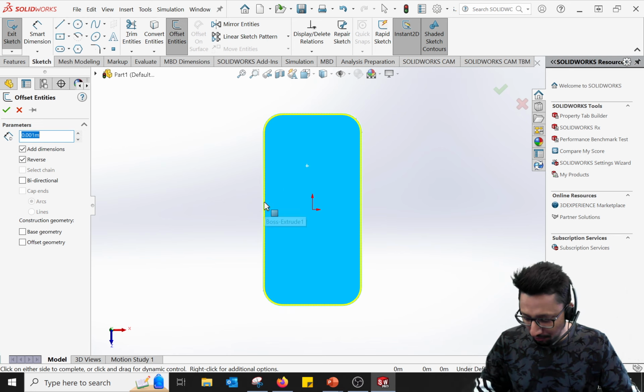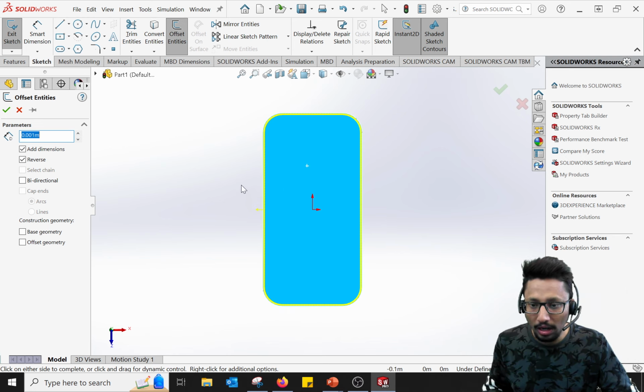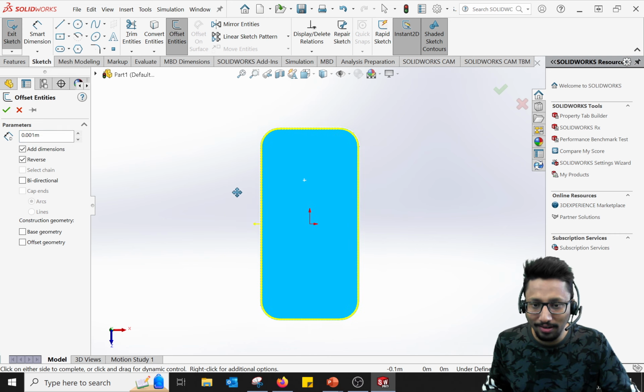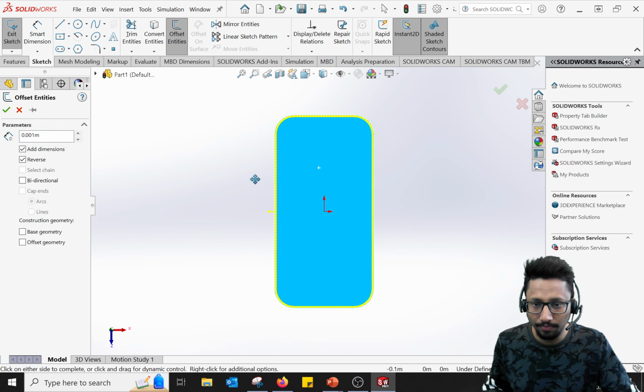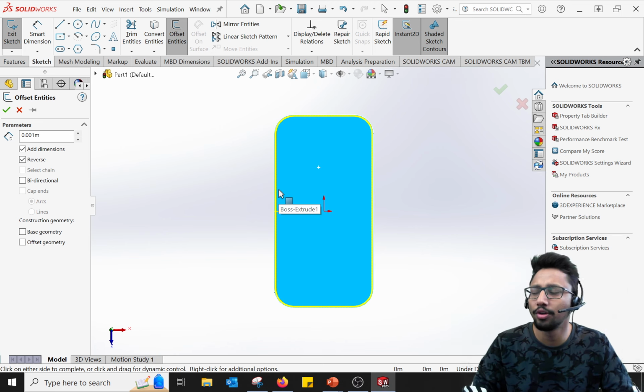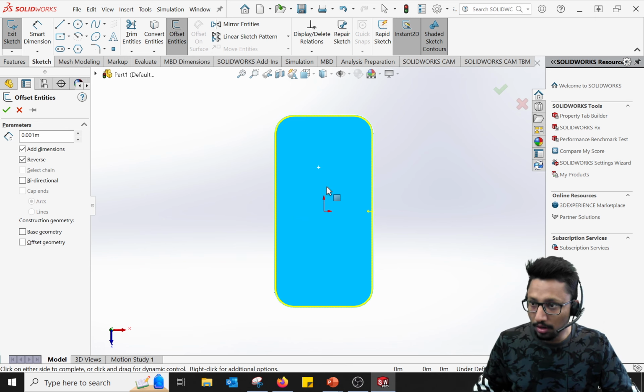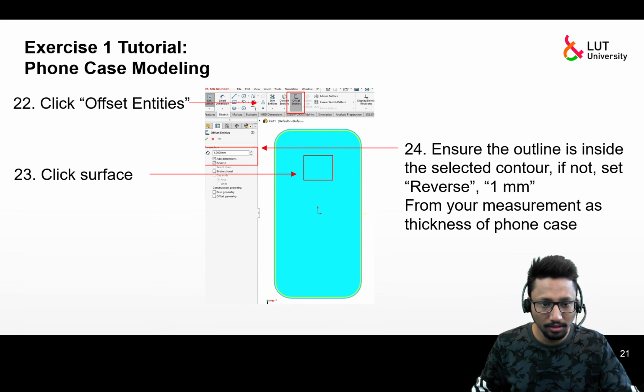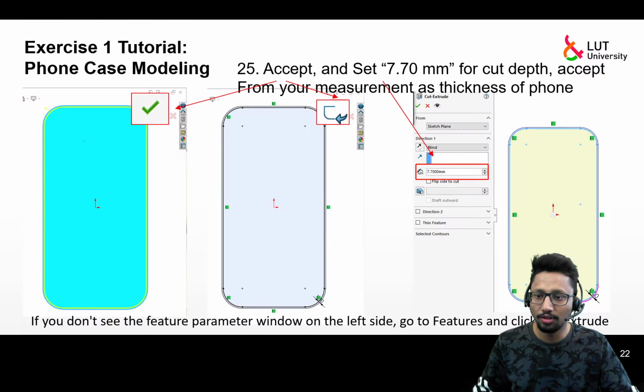If you want to pan view, press Control and then press the center cursor and then you can pan view, correct? So these are the shortcuts which are not provided in the slide, but just for your information. Okay, so if I follow the slides correctly, perfect. Okay, we covered this part.